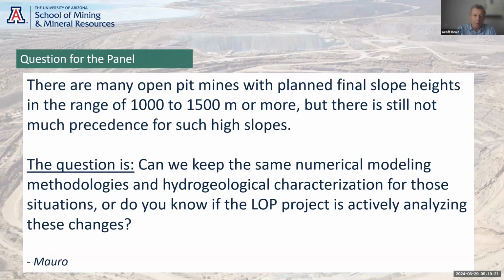And so, to take your example, Jim, you took the proactive measure of putting in a drainage tunnel all the way around the toe of your slopes. And what that's enabled you to do is have confidence that you can vary the mine plan without major implications on the overall slope performance due to water.